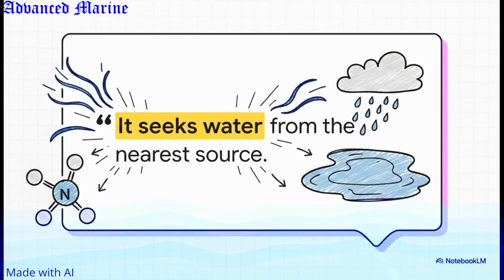To really understand how to contain ammonia, we first have to understand its core behavioral quirk. You can almost think of ammonia as this thirsty, water-seeking entity. Now, in its anhydrous state, meaning completely without water or humidity, ammonia is actually considered a relatively non-corrosive, stable substance. It basically just sits there. But the exact moment it finds even a tiny trace of moisture, its personality flips completely. This water-seeking property is the fundamental challenge engineers face because, well, in the real world, moisture is everywhere.